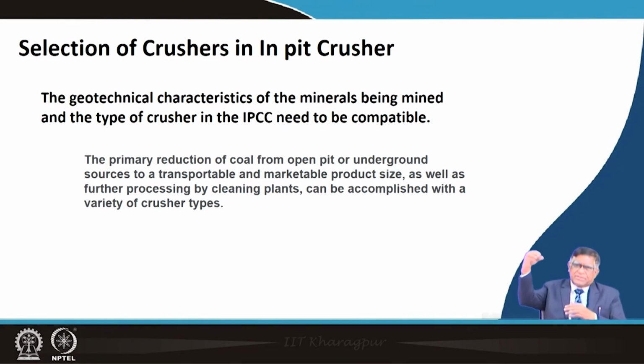At that time the next lot of material to be crushed is poured in. As a result, because the crusher has not been able to crush, the material is not flowing out. So, a situation of choking arises.